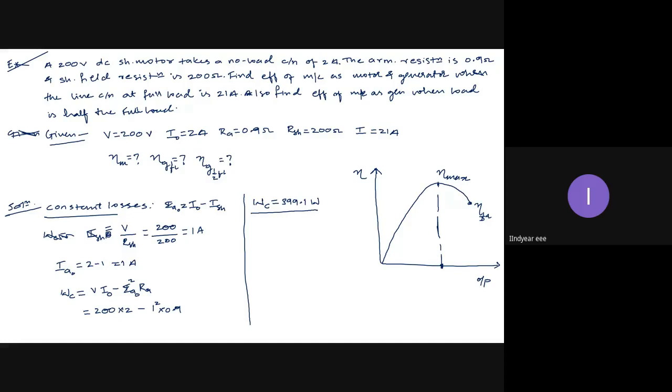Now, when the load is 500 kilowatts and the transformer rating is 750 kVA, what should be the operating point of the transformer? I should keep the operating point near the maximum efficiency point. The load factor of a transformer should be nearly equal to the maximum efficiency load factor. We know how to calculate the load factor of a transformer for maximum efficiency. It is always equal to the square root of copper losses by iron losses. So that is the load factor.